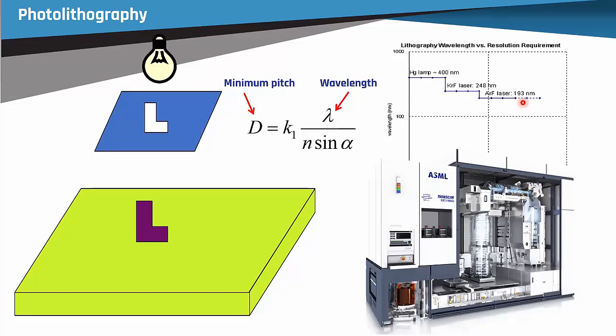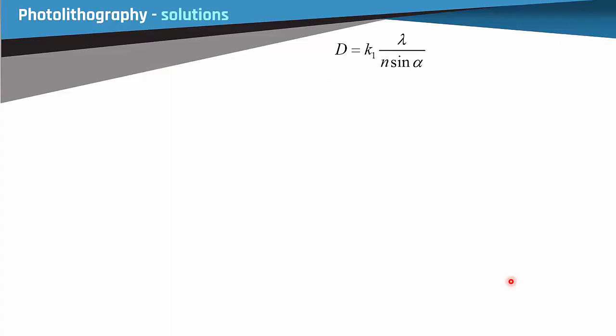And the reason it hasn't changed, or there are several reasons it hasn't changed, but even making this 193 nanometer laser, you need this huge and really expensive machine with really big lenses, and it has been a challenge that everybody knows we want to go past that 193 nanometer wavelength. And that's why that professor was saying 90 nanometers, we reached a peak, we did all the tricks we can't go any lower, Moore's law is dead. Well, guess what? Seems that process engineers are smarter than that professor, I guess.